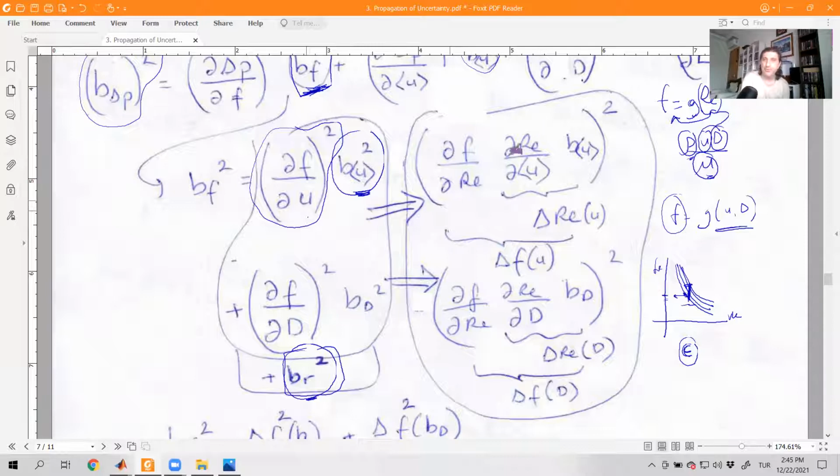If you multiply those two, the partial derivatives of Reynolds number cancel, so it's going to be this expression. Now, if we had an analytic expression, this part would be very easy, as we could directly find the derivative. But unfortunately there is no expression here. Well, there is an expression for the relation between Fanning friction factor and Reynolds number, but the aim of this example is not to use that one, but to use graphical procedures. This should be read from the graph.